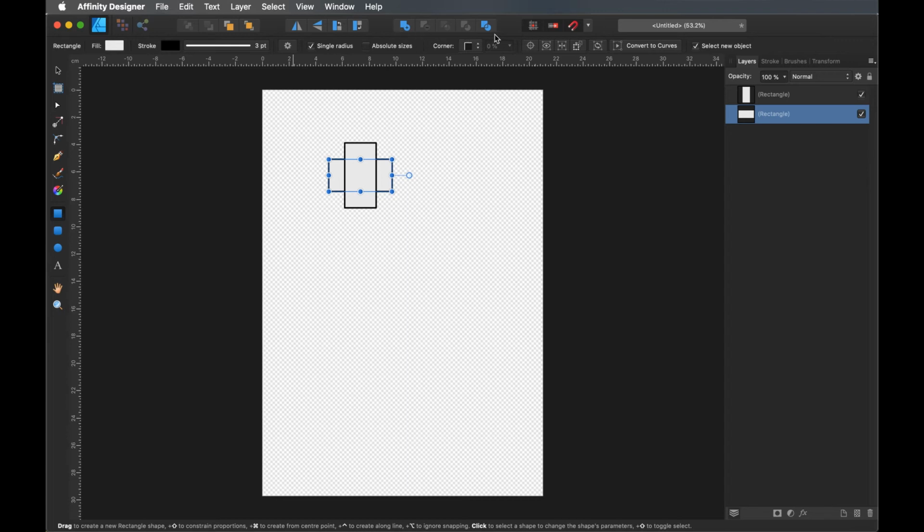Here you've also got your geometry tools, which in Illustrator are called your Pathfinder tools. So they'll tell you what they are as you hover over them. So you have add, which is reasonably obvious, it adds the two together. Subtract, which takes one away from the other. Intersect, XOR, and divide. You can see what each of them does. So intersect will only show the little area, say in that pie chart there. XOR will have everything but that area, and divide has everything in 3 separate options.